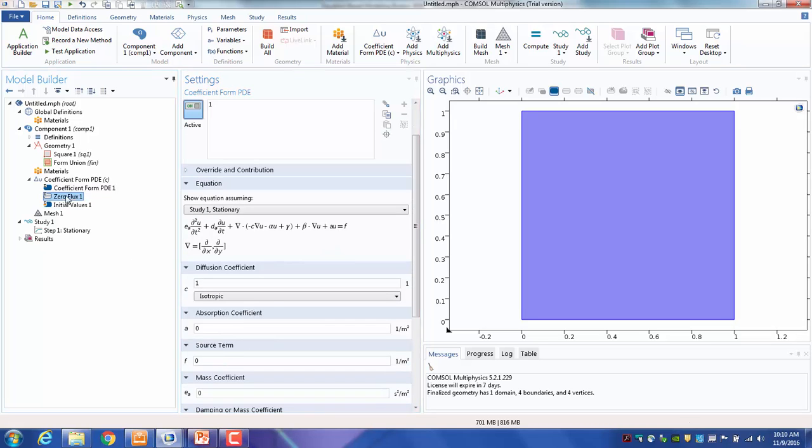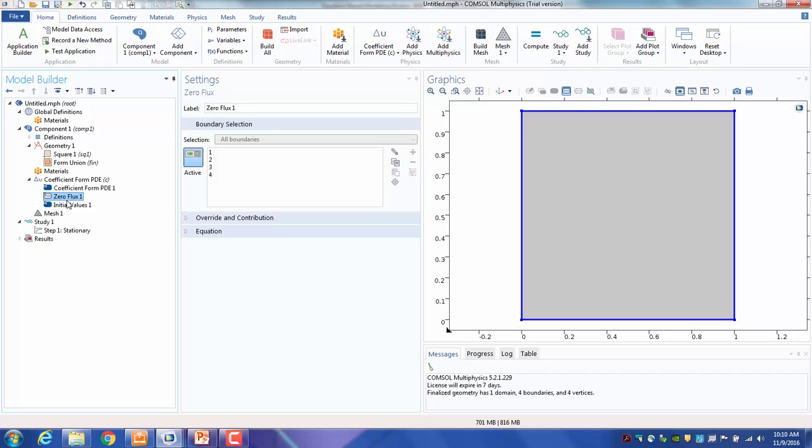Then the next thing is the boundary condition. The boundary conditions are setting the Neumann boundary condition to 0. That's the default. So basically, physics-wise, that's no flux of the quantity you are conserving. So in a chemical reaction problem, this would be no concentration crossing the boundary. In a structural mechanics problem, the momentum flux being stress, it would mean free of stress. But if your boundary conditions are different from the default, you specify them.